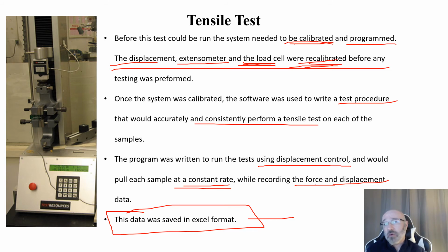So we decided to not use the program for that, because it would have been a little bit more work to reprogram every single test specimen into the software, rather than to just run it, collect force and displacement, and then use that information with the cross-sectional area that varied for each specimen in our hand calculations, or whatever we choose to run the calculations in. I believe I used Excel for that later when we calculated our stress and strain.